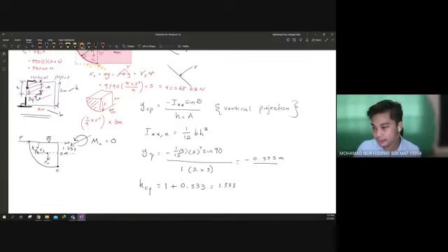Okay, from here you can see the line of action here. This is the line of action, from here to here, line of action FB. You need to know the distance here. This is actually the standard distance of the quarter circle centroid. If you look at the table, the centroid of the circle is C equal to 4R over 3 pi.